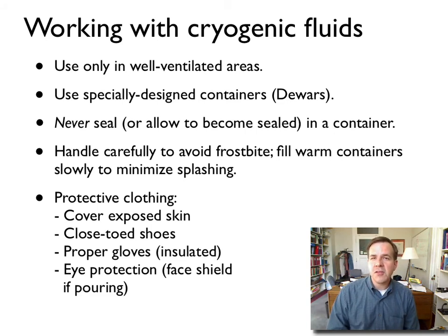These Dewars are designed such that it is not possible to trap or completely seal the cryogenic fluid in the container. There's always a pressure relief mechanism to prevent an explosion. What goes along with that is that we should never seal or allow to become sealed a cryogenic fluid in a container. Right? And you have to be a little careful. Of course, you need proper maintenance of your containers and your Dewars.